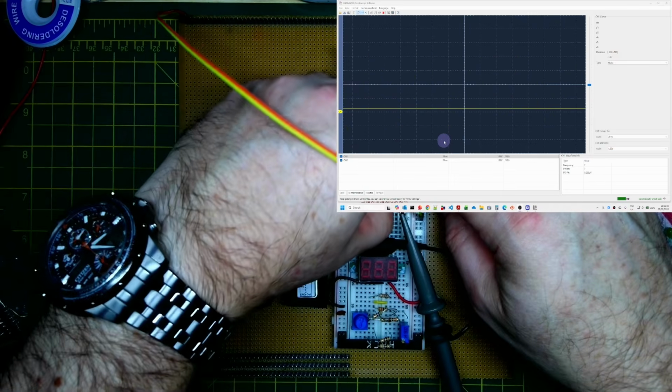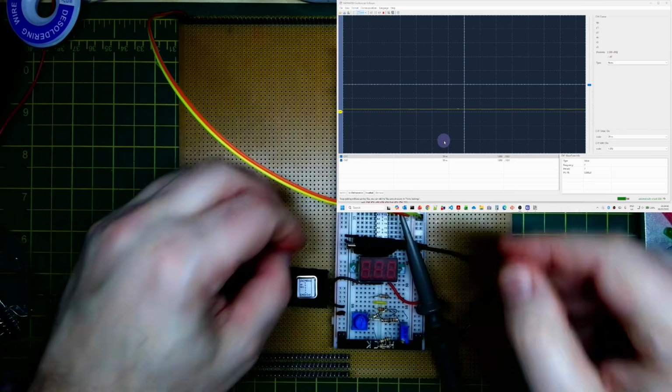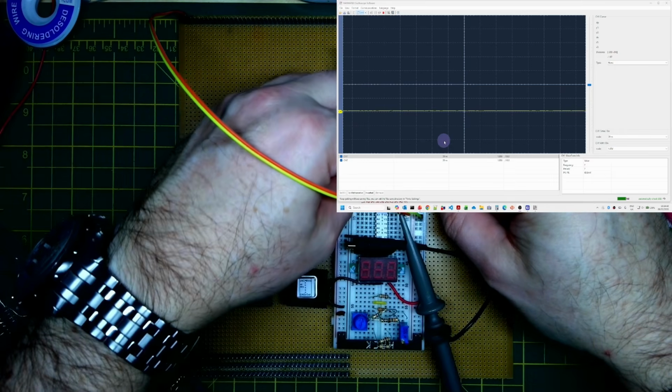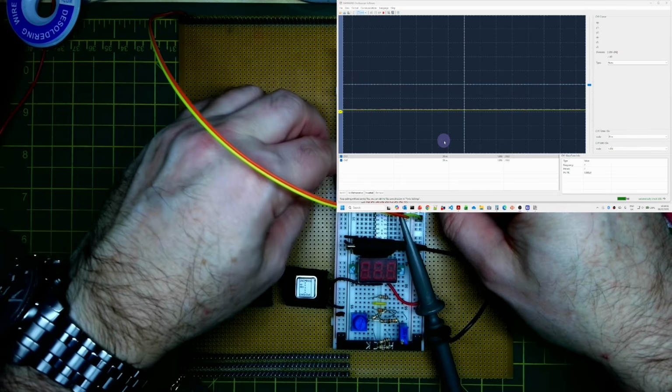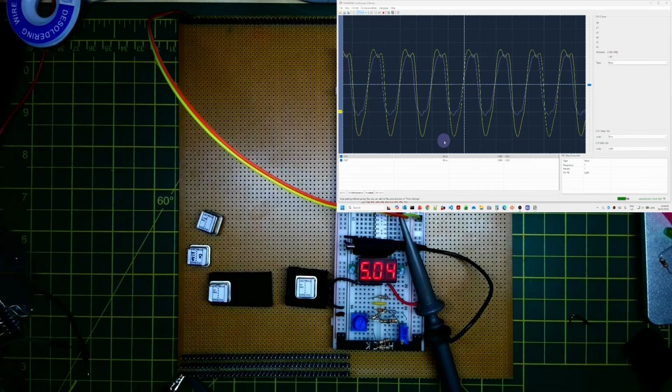Now let's try 25 MHz. So this is the frequency that we use for the video controller dot clocks, because this is the frequency needed for a VGA video output at 640 by 480. Okay, so it's still undershooting by probably a little bit more now. We're almost up to about -1.8 volts here, in fact. But the output of the chip is still sort of going to 0 volts.